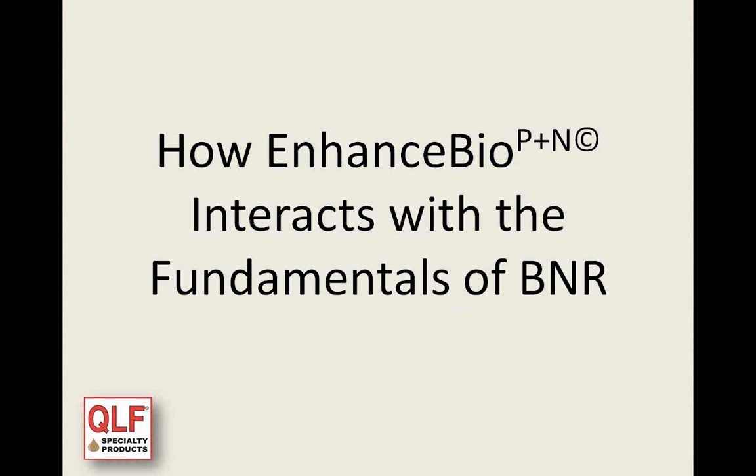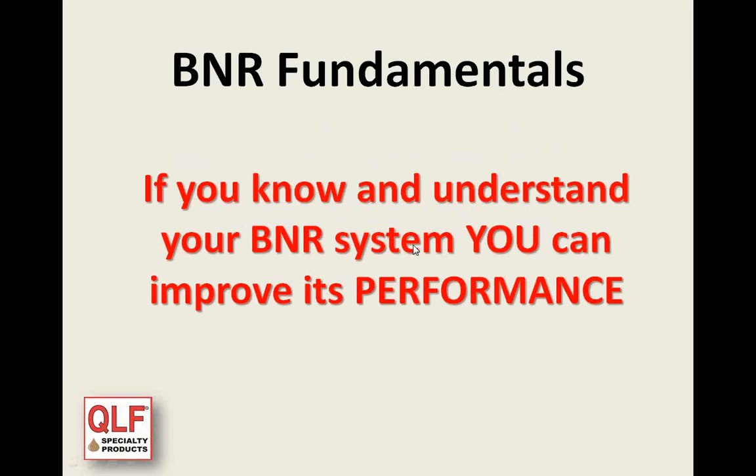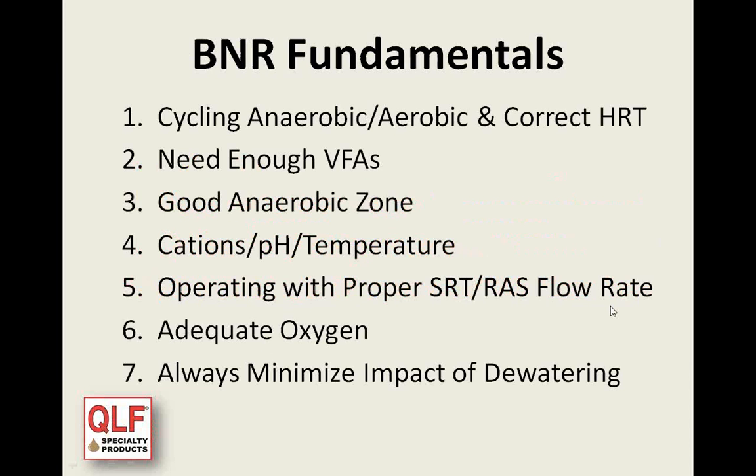Now we're going to go through how our product interacts with the different fundamentals of a BNR system. Again, if you know and understand your BNR system, you can help improve its performance. I pulled out 7 what I consider fundamentals to a good operating BNR system. Cycling between anaerobic and aerobic and correct HRT or hydraulic retention time.